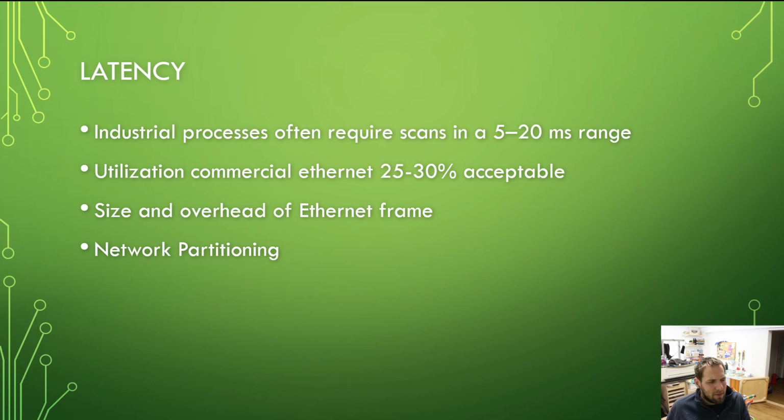So there is a lot going on in the industrial environment. For those who've taken my PLC class, you know this: we're programming things and it's like, oh, I gotta stop this part at this location. I don't want it to go past it. A lot of simple PLC programs are running in the 1 millisecond loop range, so 1,000 times per second. Even slow ones that we've written in classes are only like 2 or 3 milliseconds, so 300 to 500 times per second. So we're running really fast. As you get to larger programs, it might take a little longer, but still, they're running 50 to 100 times per second. So definitely something you need to be aware of.